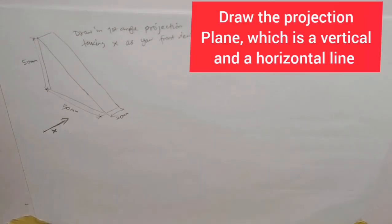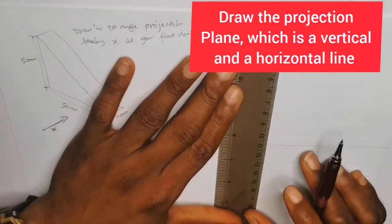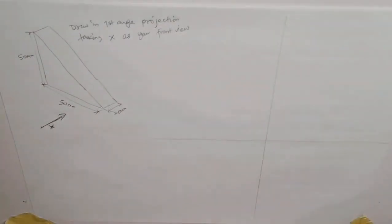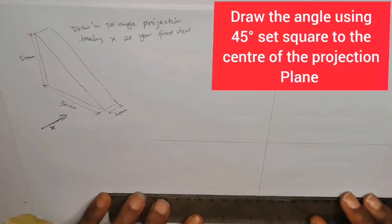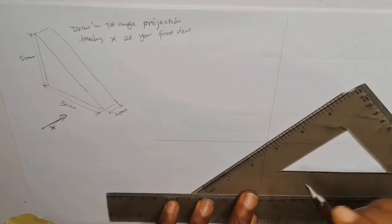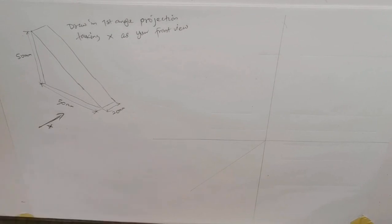First of all, we'll draw the orthographic lines, which are a horizontal line and a vertical line. It should be a construction line. Construction lines are thin continuous lines. And also I will draw my angle at 45 degrees.